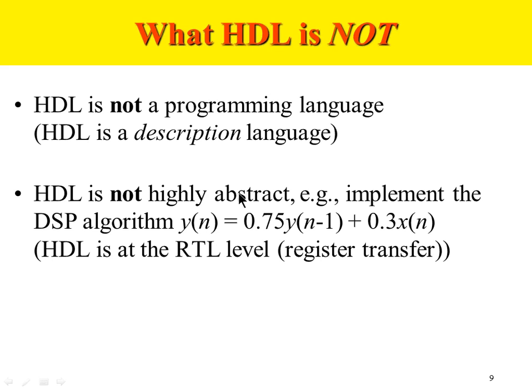Verilog is more abstract compared to gate level schematics and component level schematics, but it is not that abstract yet, where I can just feed any equation to it and say implement this system for me. To implement this kind of system, I have to break it down. I have to study first of all what needs to be done, break it down into stages, and then implement Verilog source code for those stages.